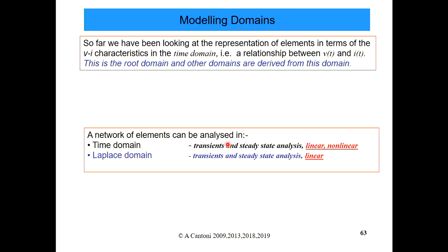Okay, so in the time domain, we can do transient, steady-state analysis, linear and nonlinear, okay? In the Laplace domain, we can do transient, steady-state analysis, but it has to be linear. In the frequency domain, we can just do steady-state sinusoidal analysis only, okay? And it should be linear, okay?